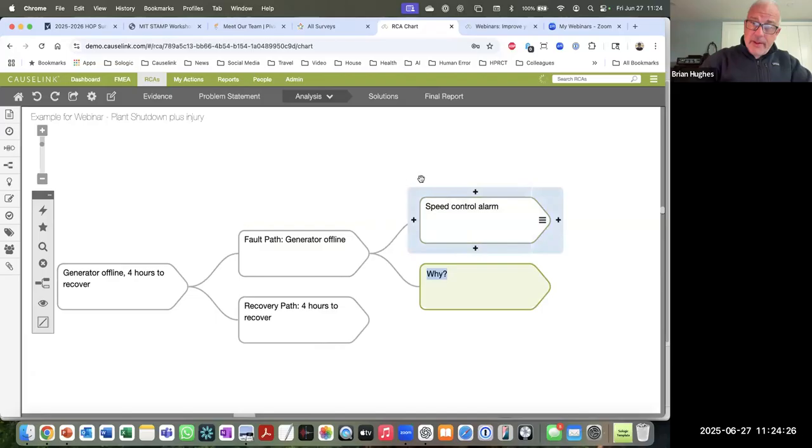What needs to happen is the operator also needs to acknowledge that alarm, or they need to bring the gen down because there's an actual problem. Sometimes, if we had a sensor failure, for instance, the operator has to go in, and I'm not exactly sure what's there, but if the operator does not acknowledge the alarm, then the machine is in self-protection mode and is going to shut itself down. So the operator did not acknowledge the alarm in the allotted time.